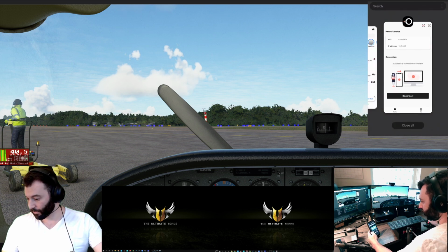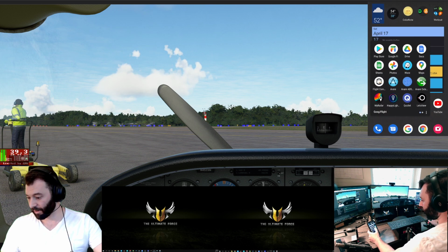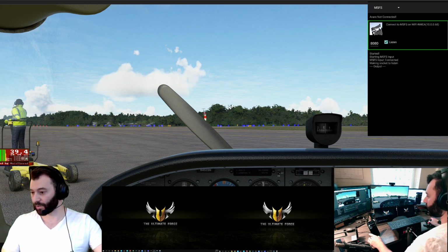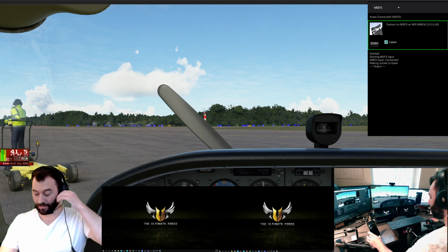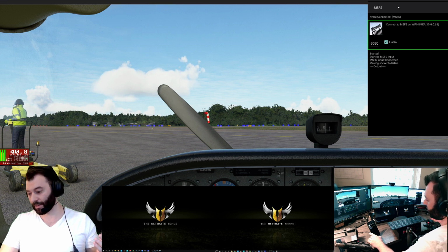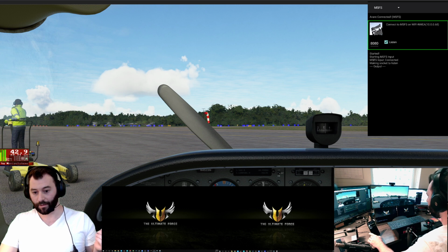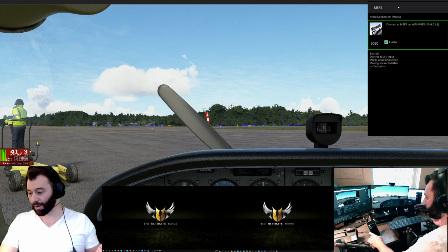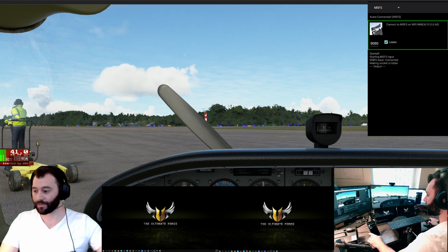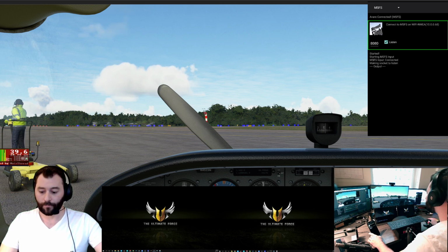On my phone, I'm going to open up the Avionics external I/O module, and I'm going to start listening. This is now my moving map app on my phone, Avionics. It's listening for our GPS data. I have it configured in the app so that it's not going to use my phone's GPS like I would be doing in the cockpit of a real aircraft. Instead, it's going to be listening over my home Wi-Fi network for my simulator GPS location. So we need to start broadcasting that. And the way we do that is...